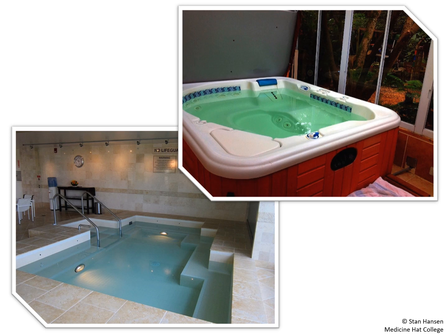Any hot tubs that are found outside dwelling units, so in a commercial environment, need to have an emergency shutoff switch. That switch needs to make sure that it disconnects all the power. It must be independent of the tub controls, so it cannot be a timer switch. It must be located within sight and 15 meters of the tub, and it has to be properly labeled. It also must activate visual and audible warnings when it's actuated, so it's a good idea to put on the label that it will do that. That way we can eliminate some nuisance tripping from people who just feel like pushing a big red button.